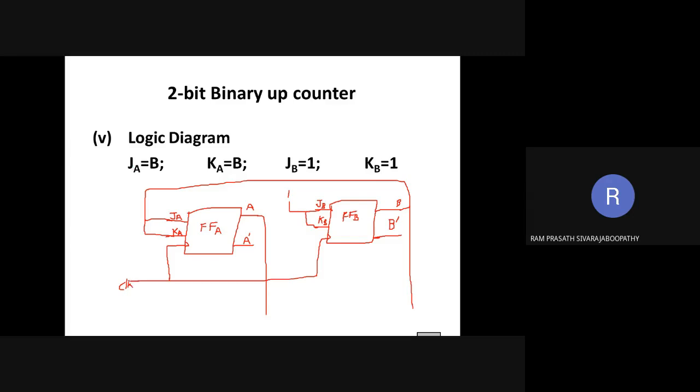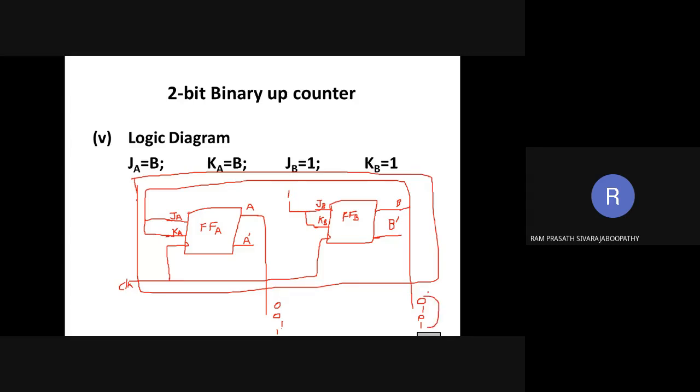So if we look at this as an IC, as a block, it will be like this. So when you give the clock input, what will come here? First 00 comes, next 01, next 10. So finally what comes? 11. So again it will go back to the previous thing. 00 is the starter. That's all. Is it clear for everyone?